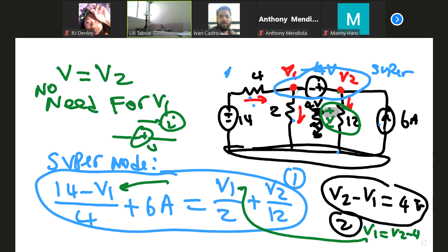The branch and all the lines and nodes connected to the branch are part of your inside supernode. And then from outside you have 1, 2, 3, 4 branches. And I write KCL for the 4 external connections to the supernode.